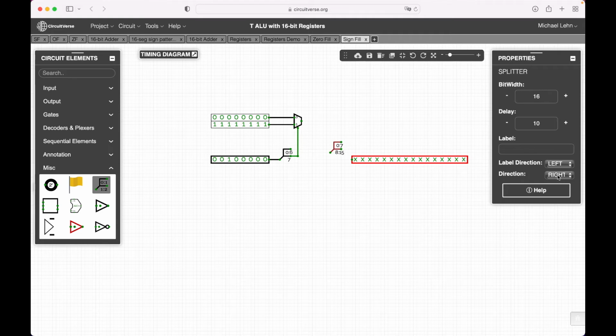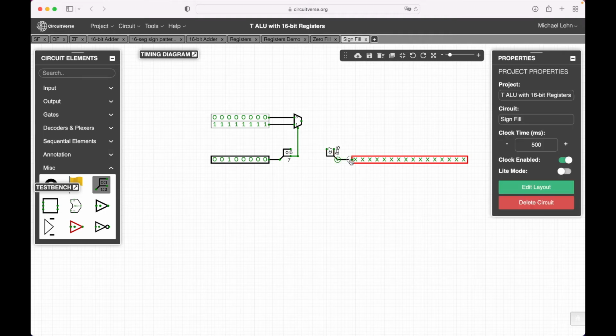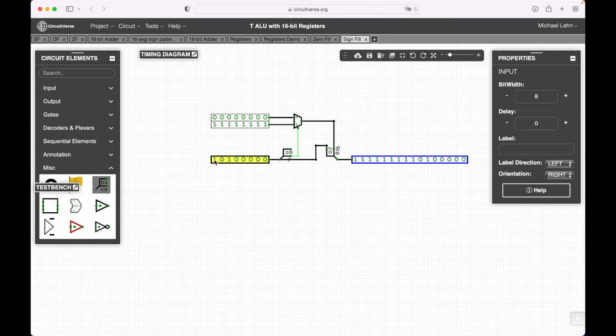So now here I want to use the direction up because then it's easier to avoid too many weird crossings in the lines. The least significant bits I get from here, from the input from this bit pattern that I called x. So I connect this with the least significant bits, and the most significant bits are what I get from this multiplexer. And now you check if the most significant bit here is set to 1, I get a 1 extension, and otherwise always a 0 extension.